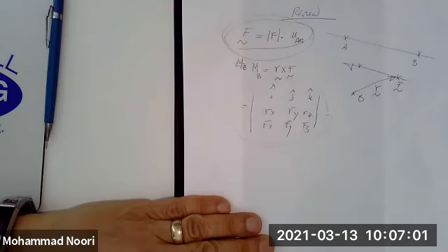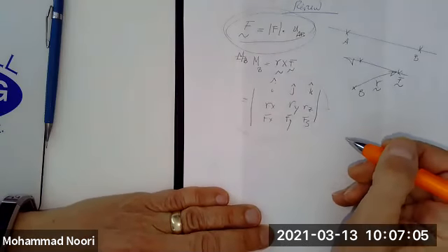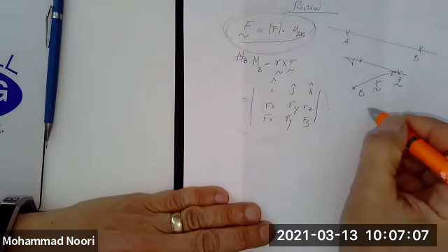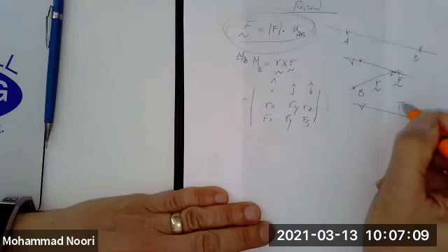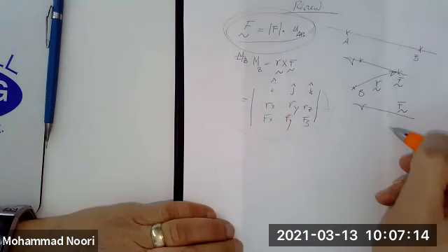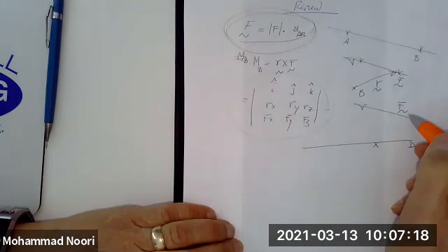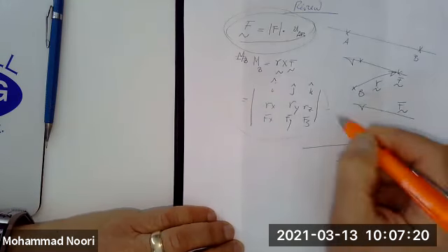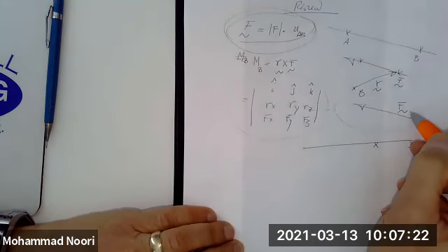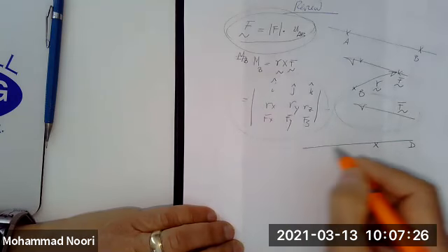So that was the second most important concept we introduced, which you really need to remember and be good at. The third one, which was related to that, was a moment about an axis. Moment about an axis is not really an independent concept. You're given an axis D, you want to see what is the projection of the moment that this force makes when it's rotating the object about this axis.